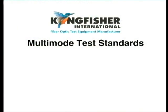Multimode test results can be very variable. However, this can be greatly improved if three conditions are met, which are embodied in recent standards. First, an LED source is used. This avoids unstable measurements caused by modal interference from laser sources.